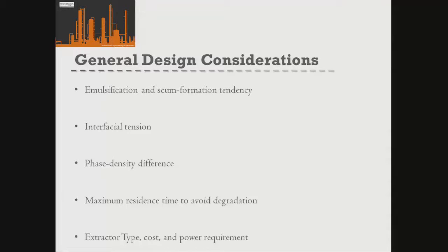And then you want to think about a residence time in your system. So how long is your material actually in your liquid extraction system for? Is it in there so long that you potentially get some degradation of your product? And that will be linked to the temperature you're running at and how close that temperature is to the decomposition temperature of one of your materials. So in that first week, we thought about penicillin, and that decomposes around 50 degrees, 55 degrees. So if you're separating that with a liquid extraction system at 20 degrees, it's probably not a problem to hold that at 20 degrees for a long period of time. But if you're having to do your liquid extraction at 50 degrees, which is very close to that decomposition temperature, the longer that stays at that hot temperature, the more likely it is to start to degrade. Okay?